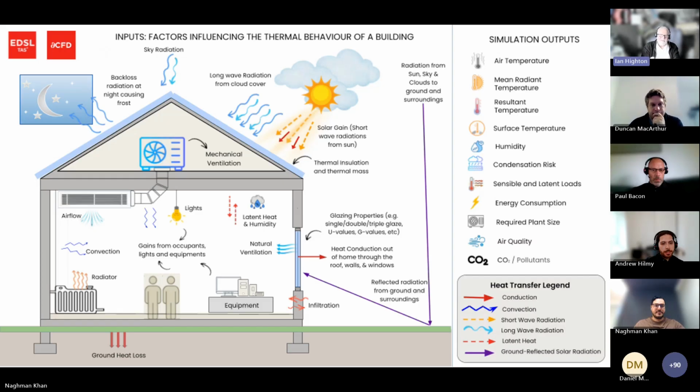And radiation is quite often overlooked. You've got two forms of radiation. This is good, actually. Sorry, the key down in the bottom right is worth a look. So you've got what we tend to characterize as shortwave radiation and longwave radiation. So sunshine, light coming off bulbs, that kind of stuff is what we characterize as shortwave, because it tends to be higher up the electromagnetic spectrum.